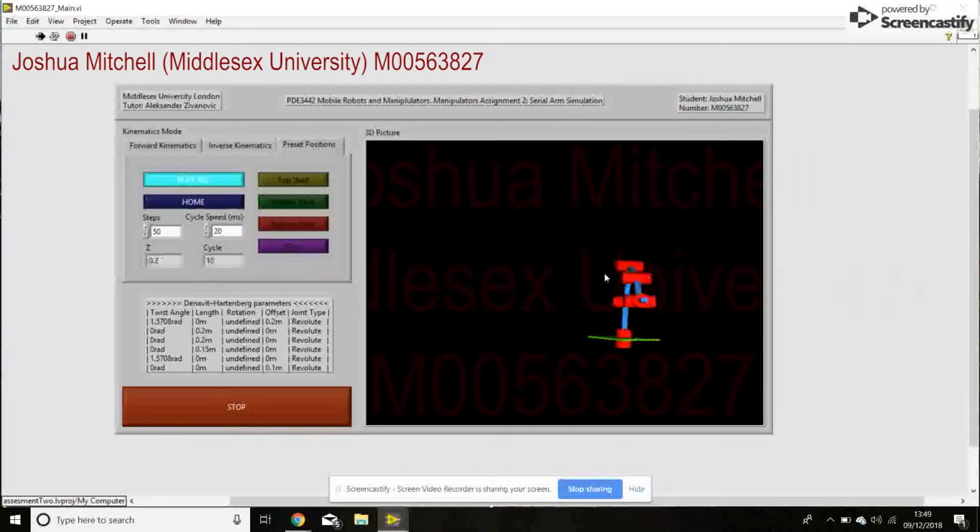There's a lot of links that aren't needed. And because only the height is required, I don't need this rotation at the bottom at all, which would obviously reduce two, because it would reduce that one and that one at the top. And these 2 joints here could be 1, so I could bring this robot down to a 4 or possibly even a 3R manipulator rather than a 6. But the number of joints was not specified. It was just for a generic serial manipulator.